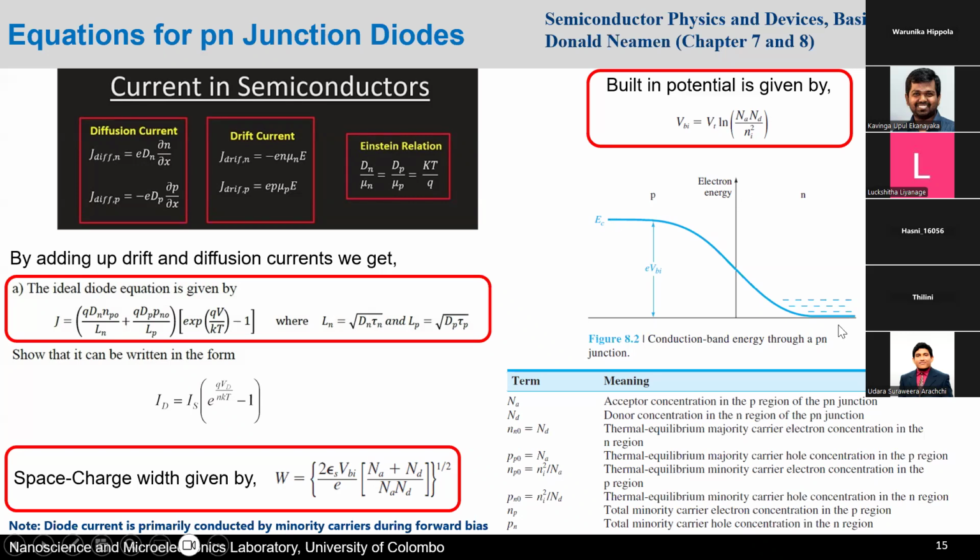So you can see that the built-in potential increases slowly from one side to another. It builds up given the electric field that spans from the N type to the P type, right? Once you have this built-in voltage, then you can use that in this equation and get the space charge width as well. So I saw some questions when I looked over the microelectronics Olympiad exam that I found from 2016, and that's why I emphasize these things. You should definitely go over these chapters and study these things before you go for the exam.